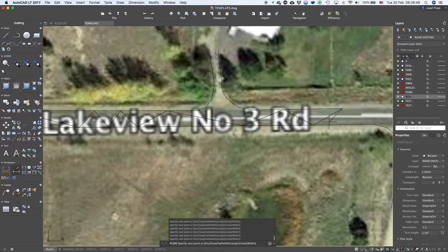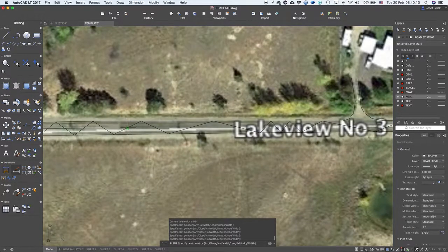So this is the easiest, quickest, and probably most accurate way how I create the center line. So I create another P line and go through the centers of these small lines, right? So just a center point, I connect this line at the center points. It's a very basic AutoCAD skills needed for this.